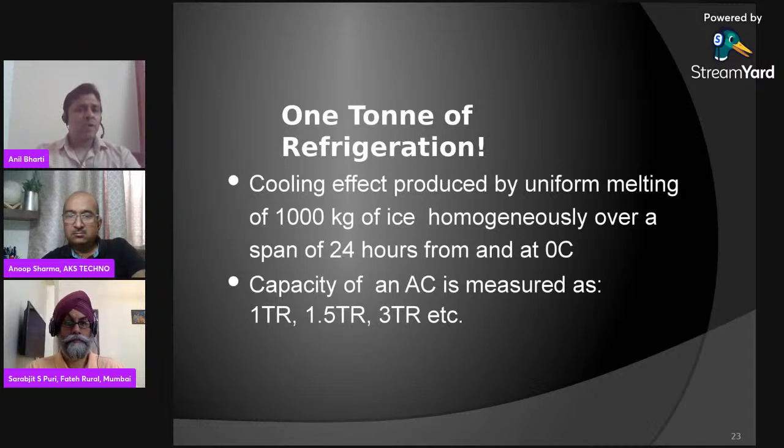It signifies the cooling effect produced by uniform melting of 1000 kg of ice homogeneously over a span of 24 hours from and at 0 degrees Celsius.